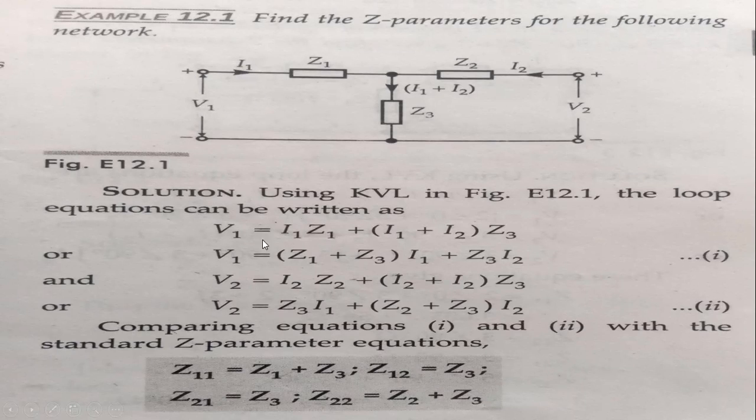So this is finished. Now come towards the plus. Again, V1 equals IZ. What is I? I is nothing but I1 plus I2 in brackets, and Z is the Z3. So if you simplify, getting I1 on one side and I2 on the other side, you will be able to find the current I1 flowing through the impedances Z1 and Z3, whereas I2 is flowing in Z2. So you can separate out the final equation, which is equation number one.